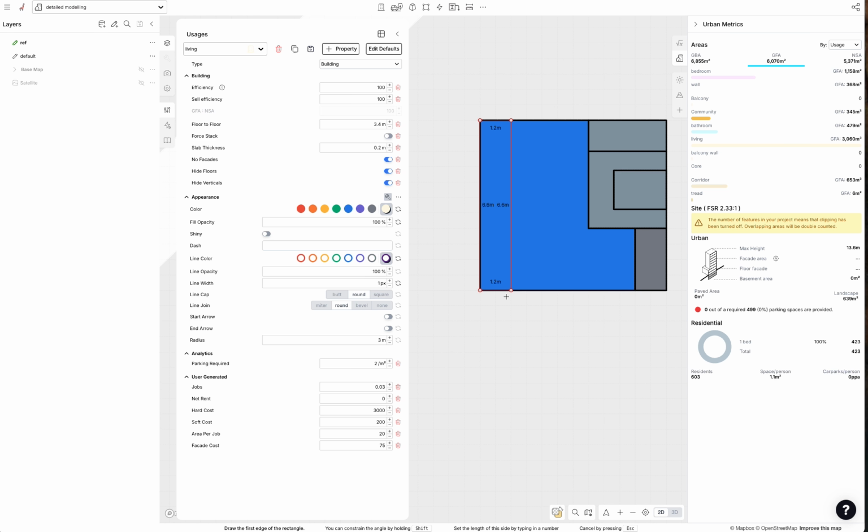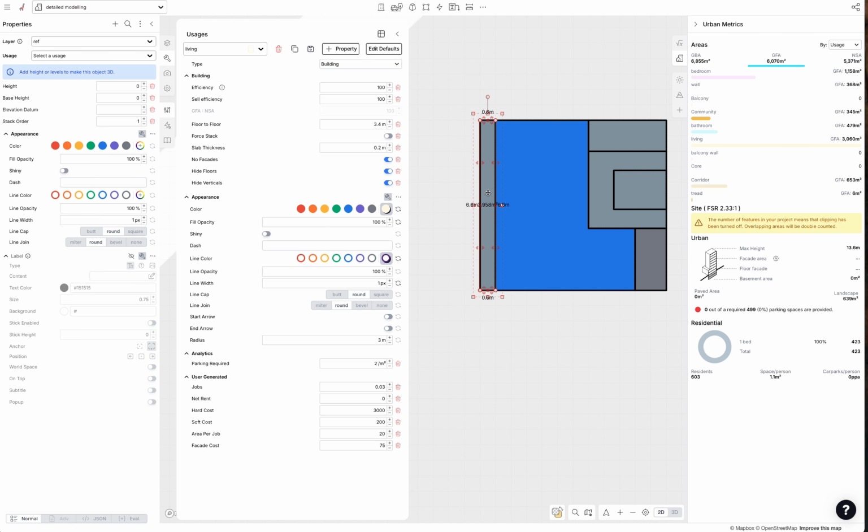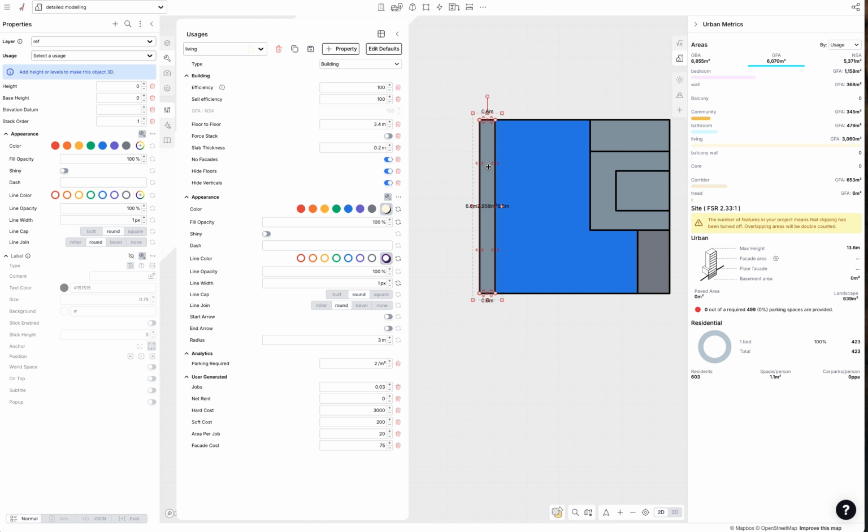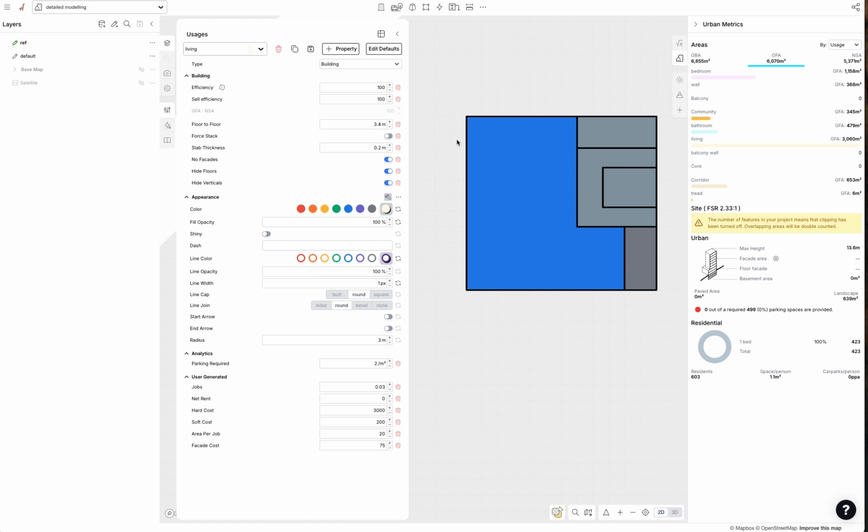But say I drew my wall like this, a big thick wall. This polygon, you can see, goes under the wall. So you may set that to 95%. Say, of this 32 square meters, only 95% is actually sellable or usable because some of it is under the wall. That's when you don't even want to bother drawing the wall. You just want to make an allowance for it. But in our case, we are going to draw the wall, so set it to 100.